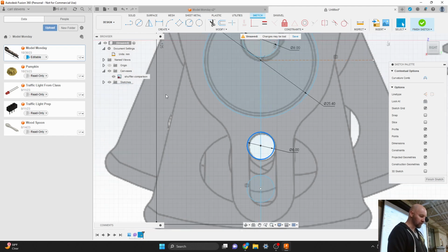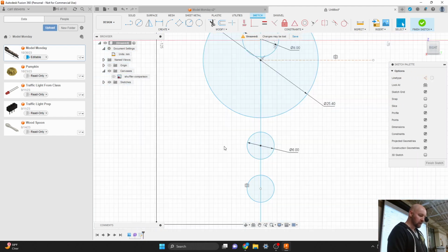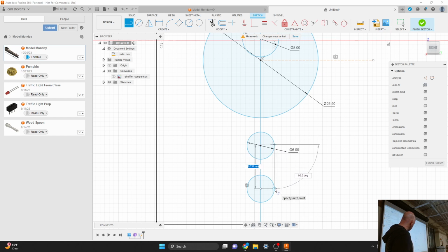All right. Now to connect those lines, there's a couple ways we can do this. In our create menu here, we can grab our line tool. It's really easy to connect, and you can find the tangent point of that second line. We indeed want these to be tangent. It's not tangent to my first circle, but it's really easy to find where it gives me that snapping point and that little blue tangent constraint icon that shows me that I'm tangent.